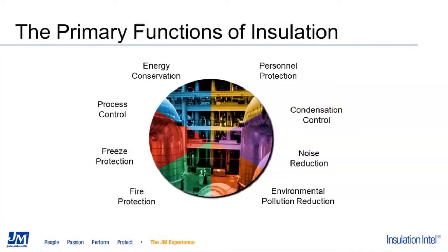Some things are going to require a high degree of fire protection or personnel protection. You may need to consider condensation control or freeze protection for subambient systems, or you may be just thinking about energy conservation, which can also help to reduce pollution within your total system.